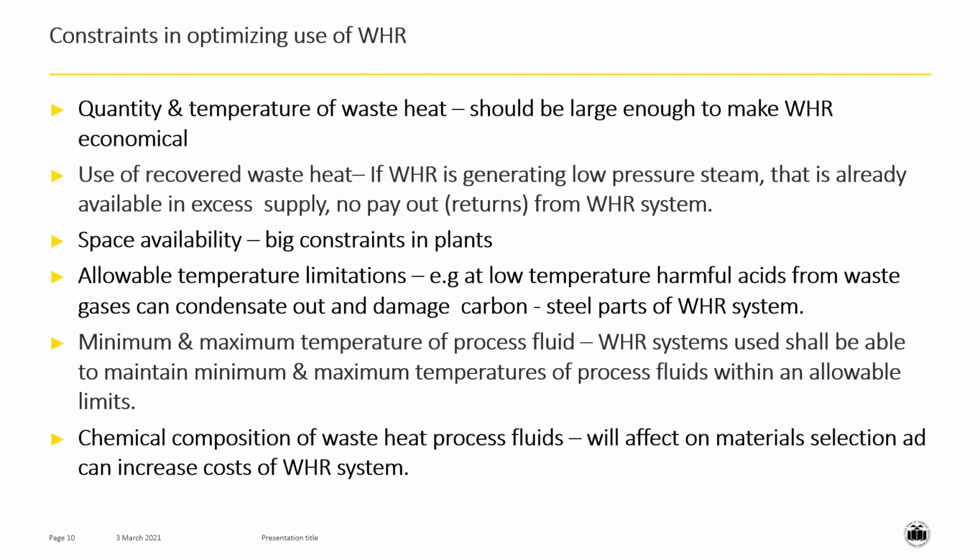Minimum and maximum temperature of process fluid. WHR systems should be able to maintain the temperature of process fluid within the desired zone. Say, in a certain industry, you may need to maintain a certain temperature within tolerance of plus or minus 5 degrees centigrade.